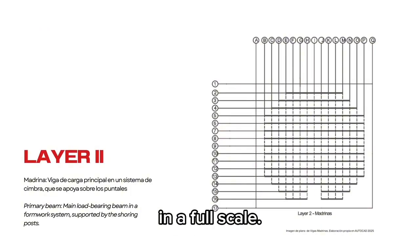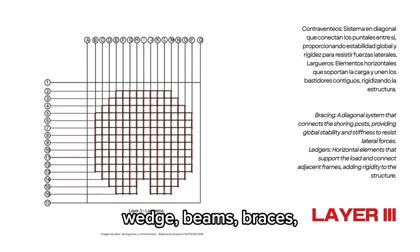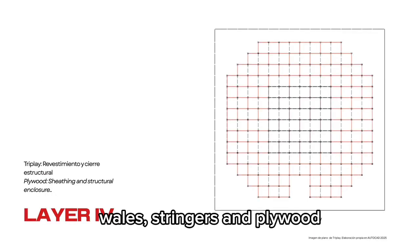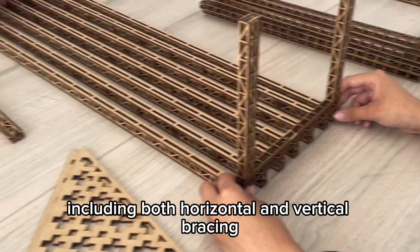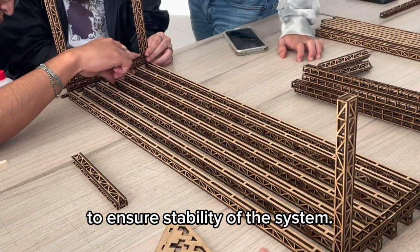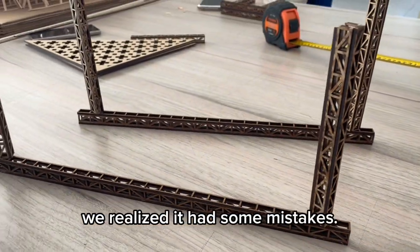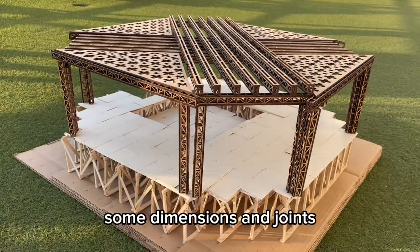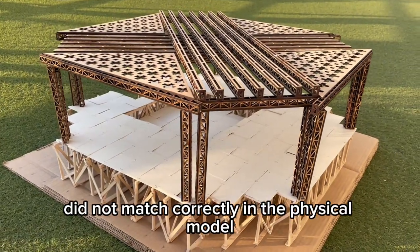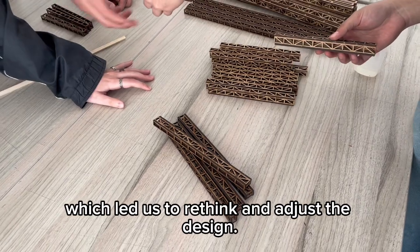The formwork was made with elements such as seals, wedges, beams, braces, wheels, stringers, and plywood, including both horizontal and vertical bracing to ensure the stability of the system. When we developed the design of the pavilion in the model, we realized it had some mistakes. Even though we followed the drawings, some dimensions and joints did not match correctly in the physical model, which led us to rethink and adjust the design.